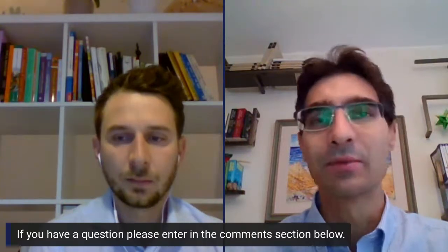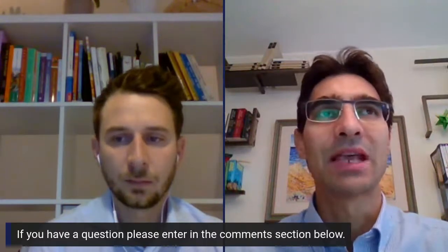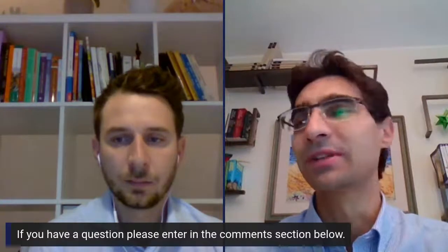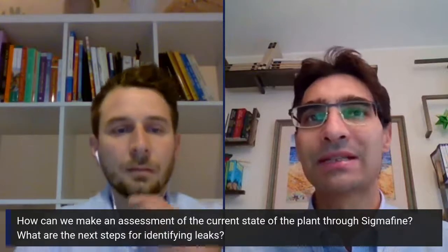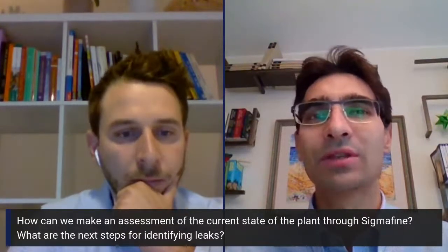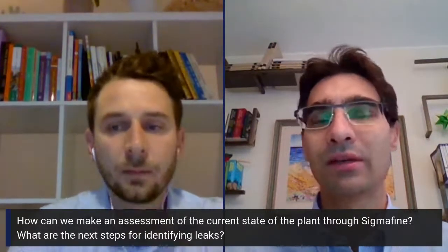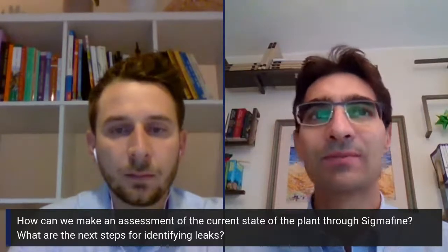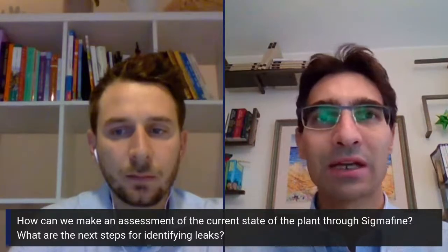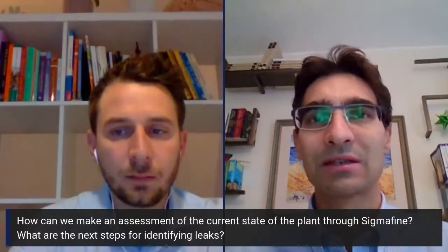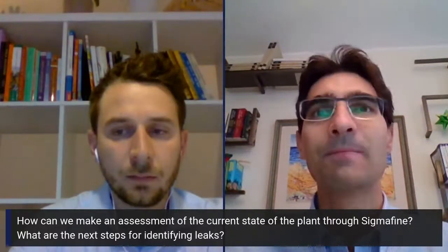And we have some cases of Sigmafine customers that detected, maybe after a few days, the presence of leaks because there was not a good agreement between the measured and the reconciled data. So they could at least spot the areas where the inconsistencies were located.